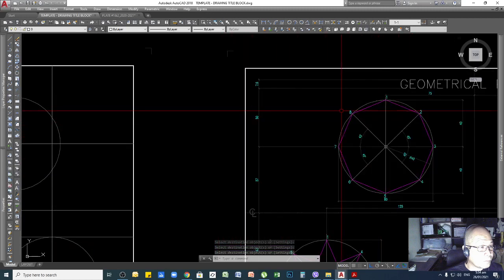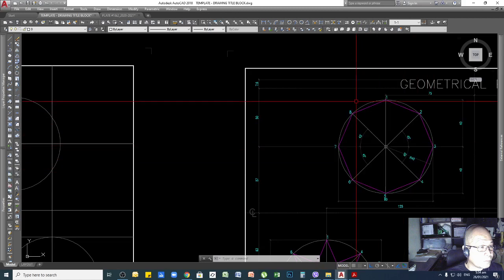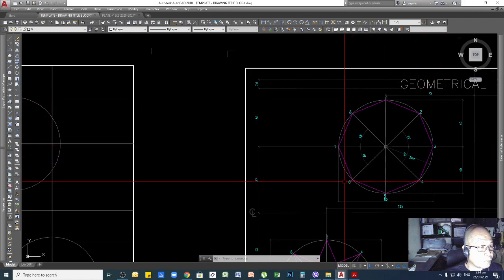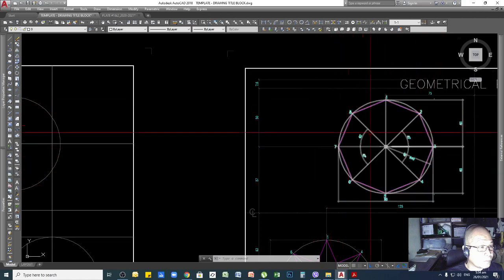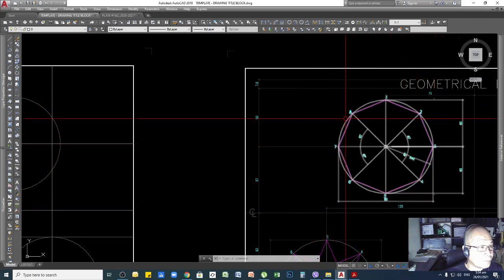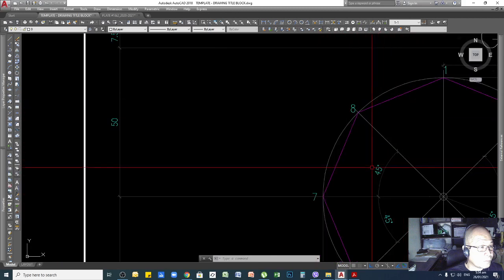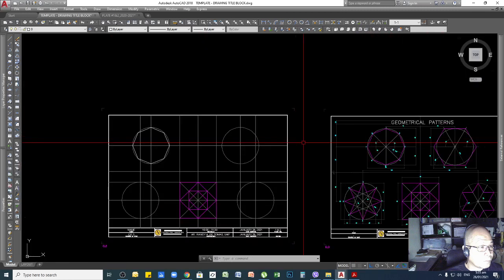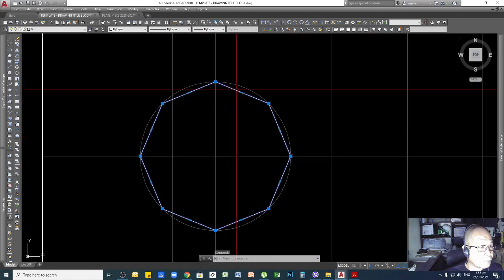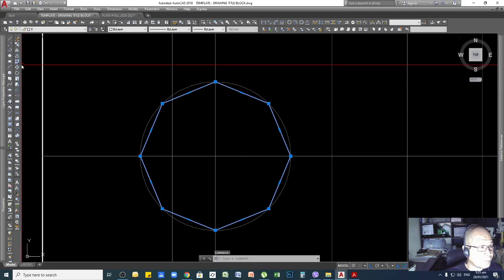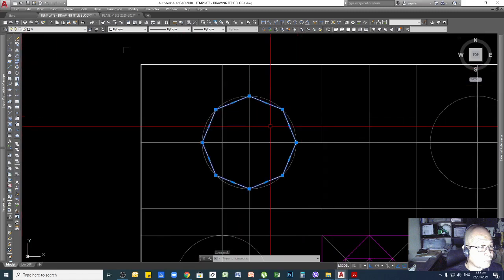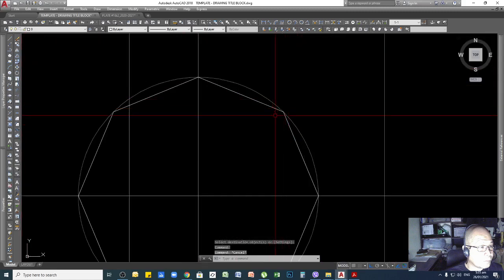This one is actually for manually drawing the diagonal line. In order to establish this point, you need to make 45 degrees, but we already have the polygon command, wherein you don't need to locate this corner.